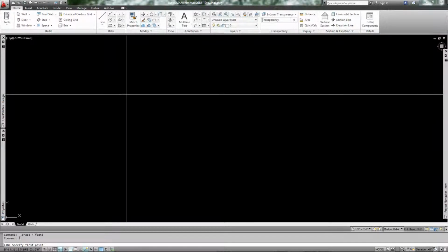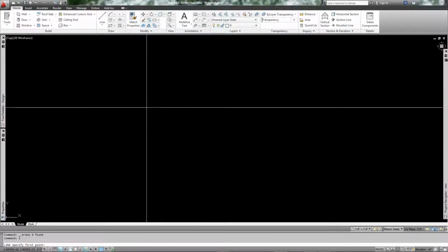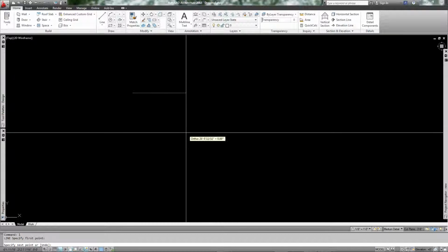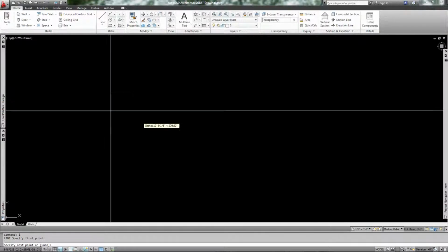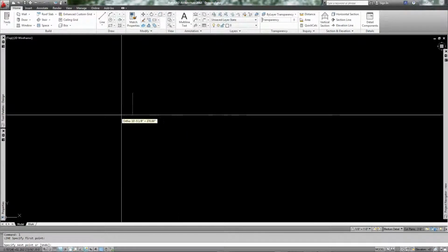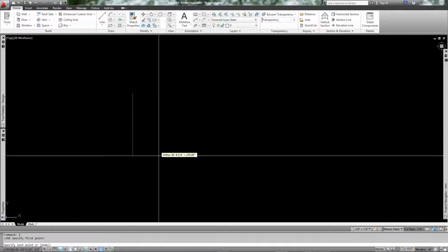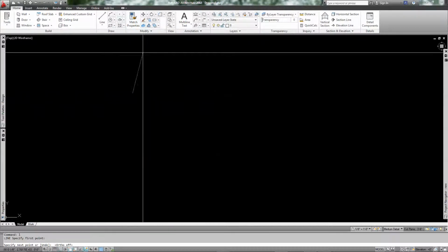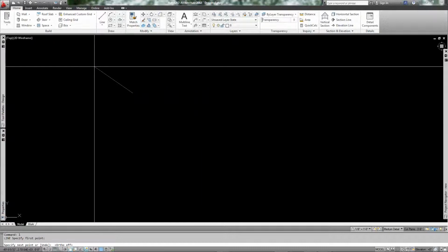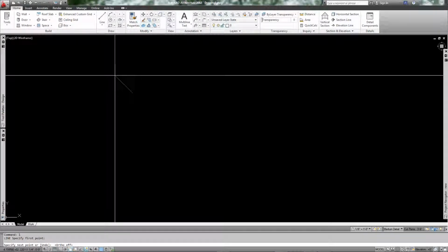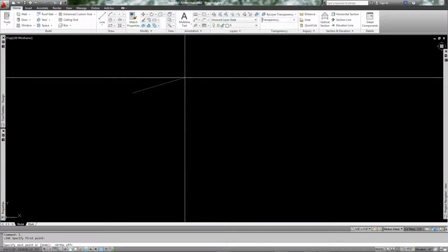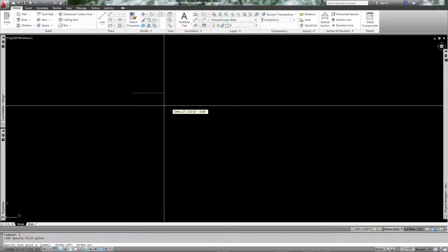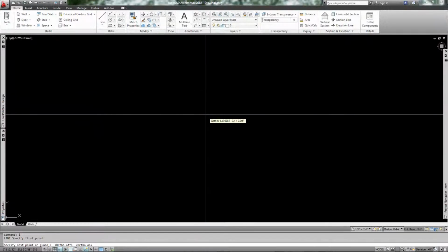Then you need to click to define a start point, and then you could choose a direction to move. If you notice, it would snap horizontally and vertically. If you choose to go at an angle, you could press F8 and you would get a free range of wherever you need to place the second point. So we'll leave it with the constraint on.